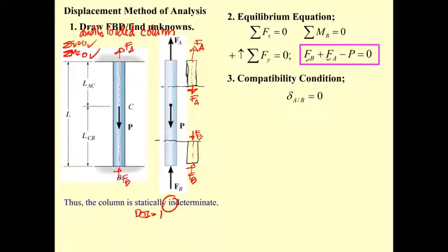This one is going to be in tension, so this portion is going to elongate. This one is going to have compression, so this one is going to have contraction. When this occurs, you may take a rubber band, hold it with your left hand and right hand, and ask your friend to pull in the middle.